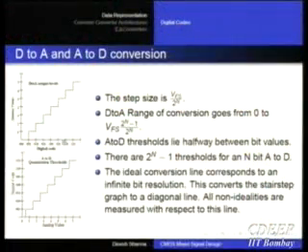That means a range, a step size from this to this, is all represented by one digital symbol. The smaller this range is, the smaller is this error of representation. But essentially you have swept an entire step into one symbol. Essentially, if you were to plot x itself versus x, you would get something like that. But now you have a stair-step approximation.